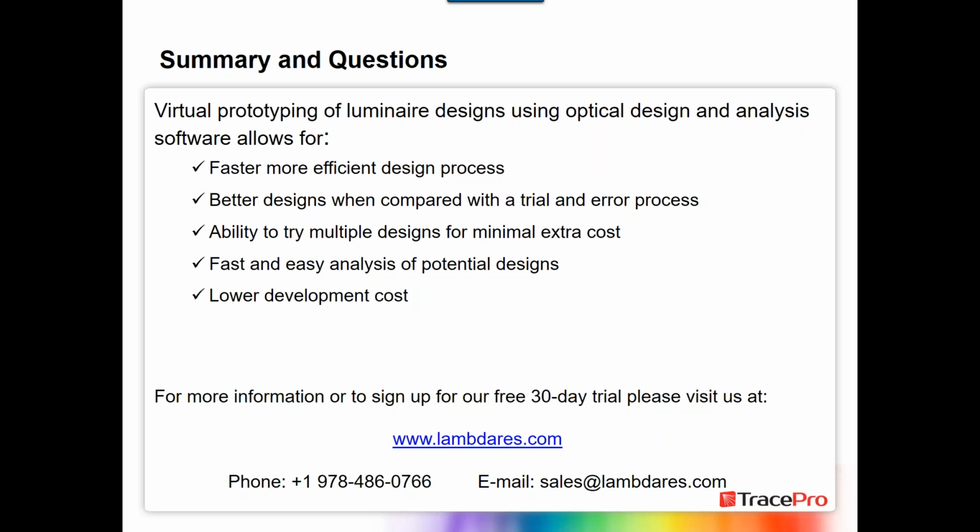If you're looking to improve efficiency, you could set a flux operand where you want so much power or so much flux on a surface. If your light source was emitting 1,000 lumens, you could set the goal on your target: I want at least 750 lumens, or I want 1,000 lumens, and see how close it can get. You could also use operands in combination, saying I want 750 lumens, but I also want a uniform distribution of light.